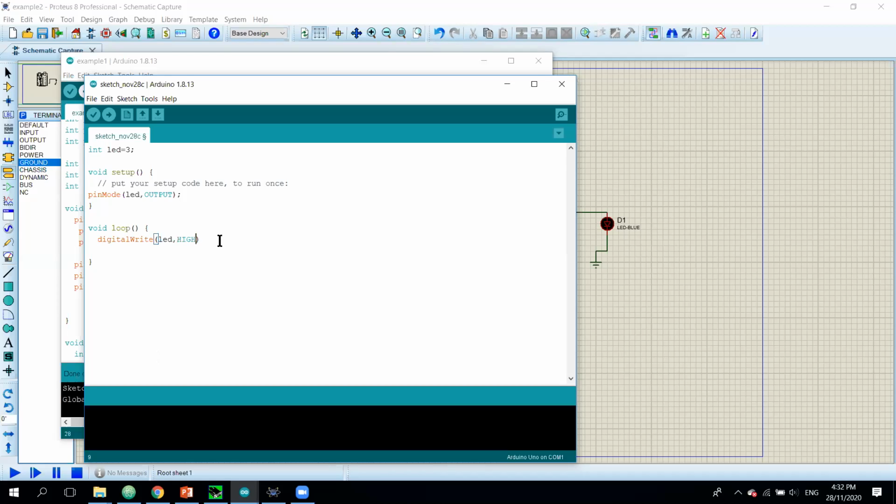Seconds intervals. So after 500 milliseconds, it will be turned off. That means you have to write this LED pin to low. So this one will loop continuously because this is in the void loop function. You all know anything in the void loop will be run continuously.